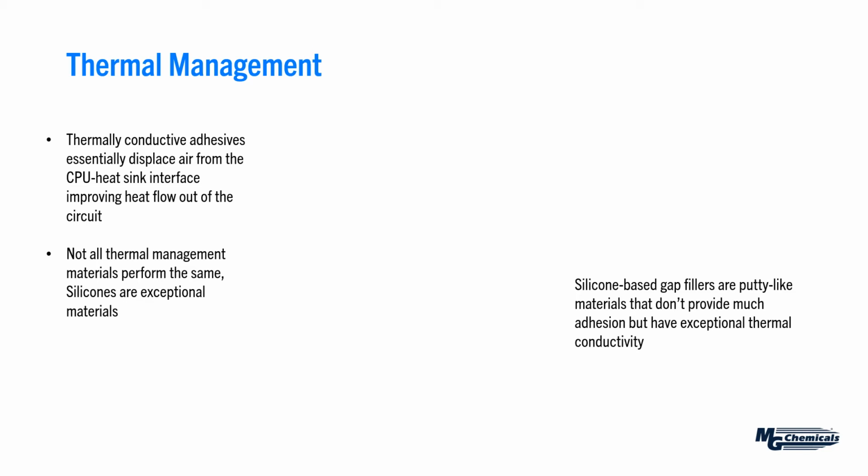With epoxy, even the best products on the market, you might be pushing 3 watts per meter Kelvin, whereas with silicones, we're typically in the range of 5 to 10 watts per meter Kelvin. So they are superior materials, not only if you need something of lower modulus, but if you just need a whole lot more thermal conductivity, those silicone gap fillers are really superior materials in that respect.